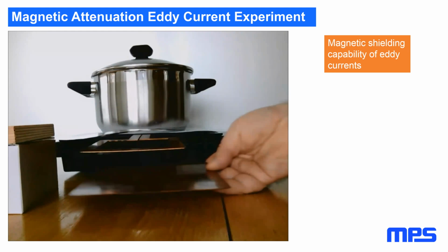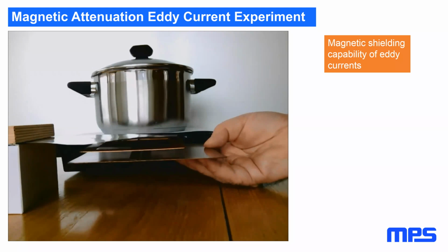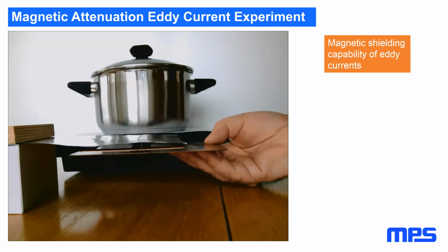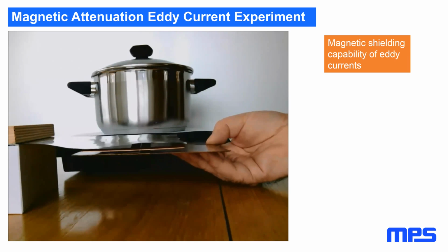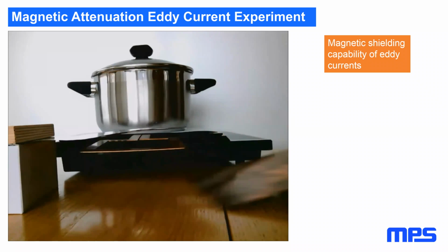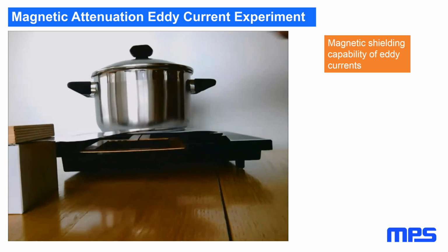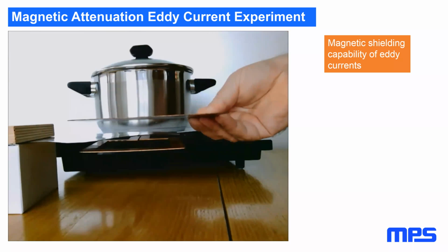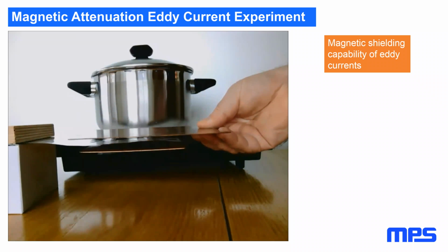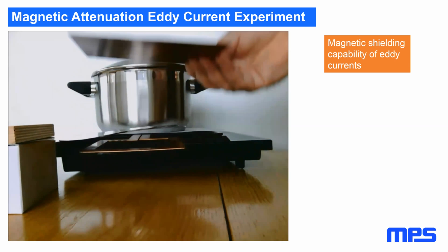And if I put a plane, a short circuit plane, a ground plane from below, you see that the flying distance of the aluminum foil goes lower. So actually, even a plane from the other side will diminish the magnetic field you create. And same goes even if you go from the other side. Now you will diminish the net magnetic field if you short circuit it.